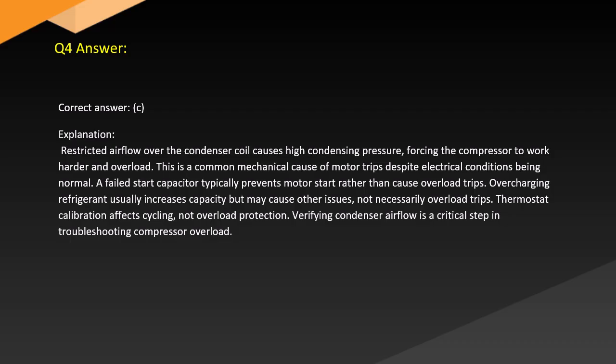A failed start capacitor typically prevents motor start rather than causing overload trips. Overcharging refrigerant usually increases capacity but may cause other issues, not necessarily overload trips. Thermostat calibration affects cycling, not overload protection. Verifying condenser airflow is a critical step in troubleshooting compressor overload.